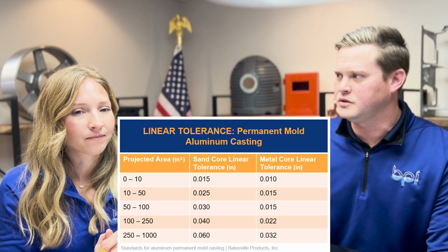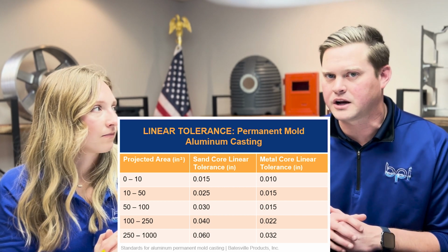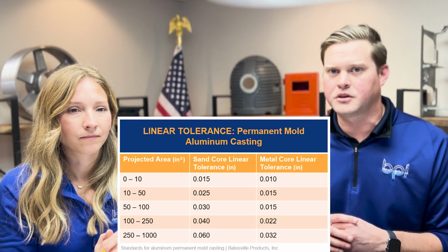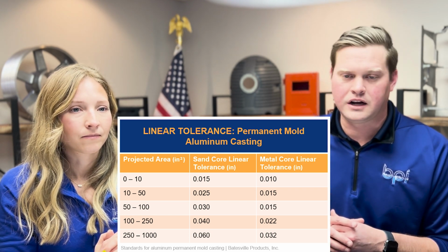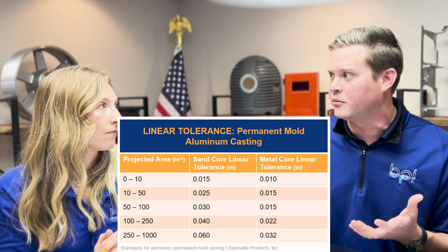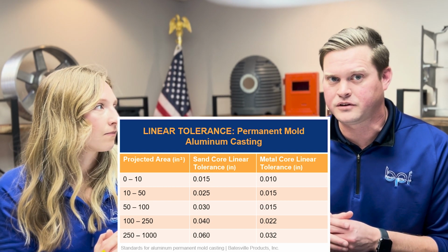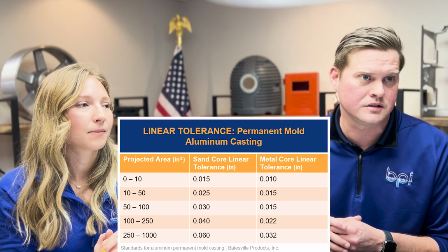I'd say the primary use that we see for cored out products is somebody running some kind of electrical or some kind of lines through it, or some other feature to really get that end application solved. It's a great process. It still gets the tolerancing on the permanent mold side of things that you would get from the steel mold, but has that hollowed out cavity inside that allows you to do those other applications.